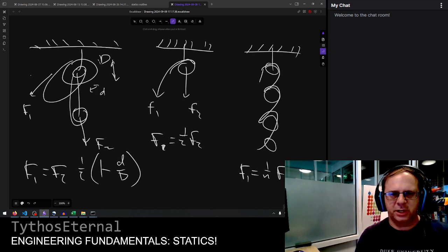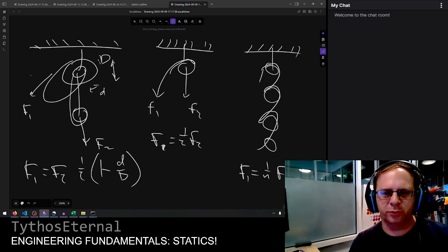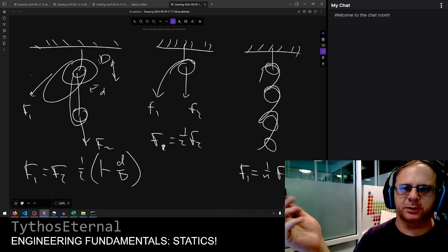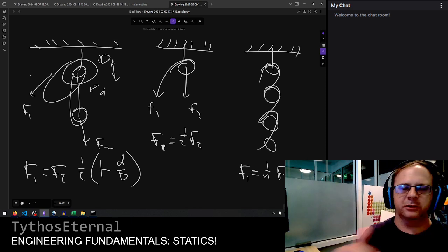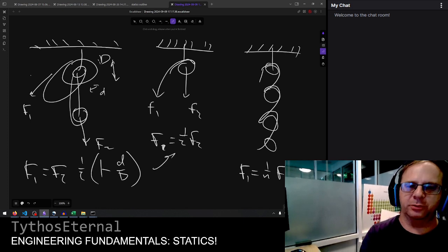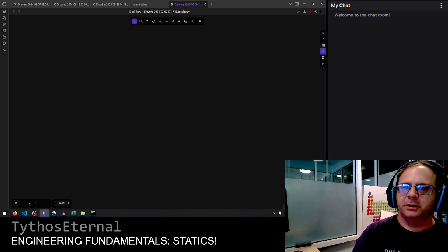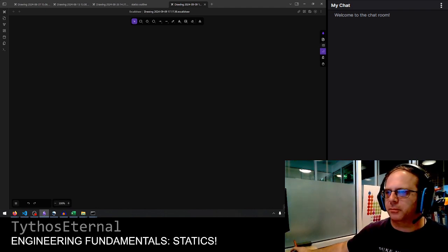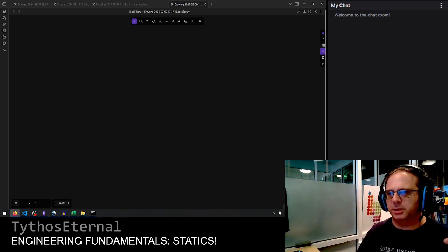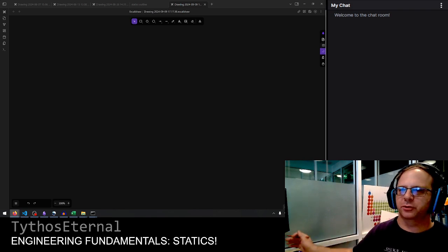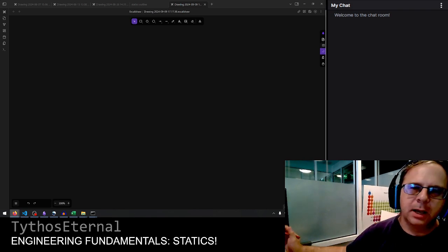You can imagine cases where one diameter approaches the other, this turns into zero, and it's like, okay, there's no point in differentiating because it's locked against itself. Or where one diameter goes to zero, you reduce to this case, right? Or where the inner diameter goes to zero. But so these are pulleys. You can see how those might be able to translate rotational dynamics into linear dynamics, or transform different scales of linear dynamics into each other.